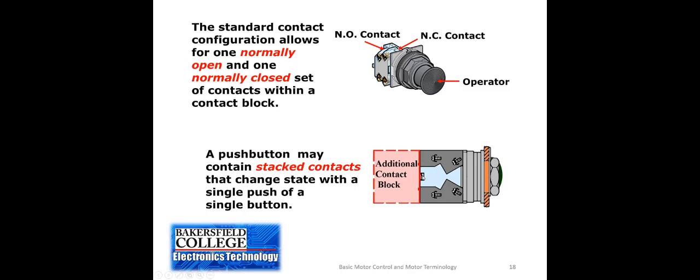But there's also a lever or a bar that is going to push or transfer that motion to the additional contact block. And it will have the same thing inside. So when this button is pressed, a little tab is going to push out of the end of it, and then that can push the next contact block.